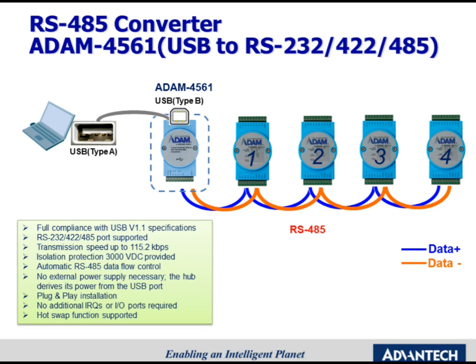One more thing, you need to install the driver on the laptop or PC before using this module, since we need this driver to convert the USB interface into a virtual COM port. Then we can use this converter to communicate with the RS485 device. You will find the COM port number in Windows Device Manager.